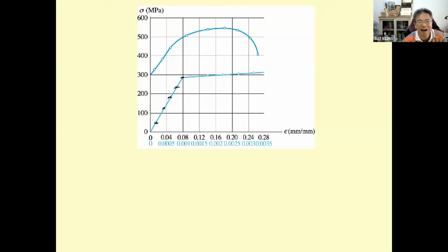Okay, this is the last part, to be the linear elastic, and then you have sigma equals E times strain. So the E is going to be sigma sub proportion divided by strain sub proportion. Again, maybe I use this one and then project it up and determine the E. It's up to you. You can use this also, or you may use this one. It's okay.